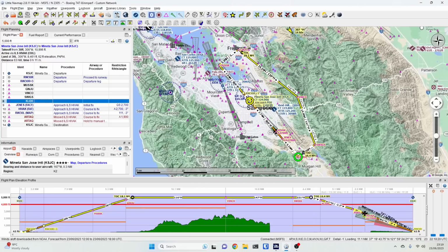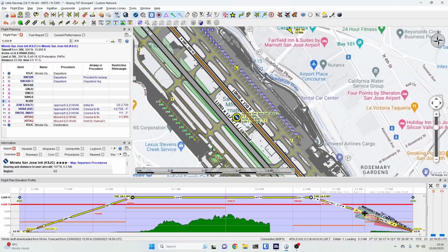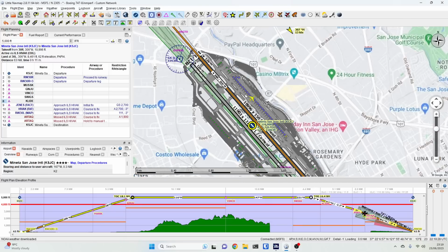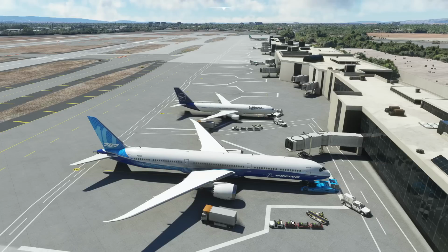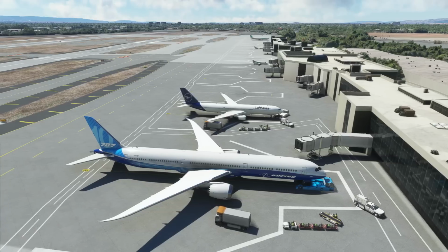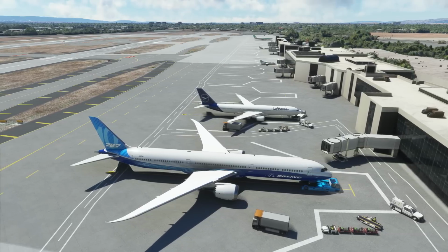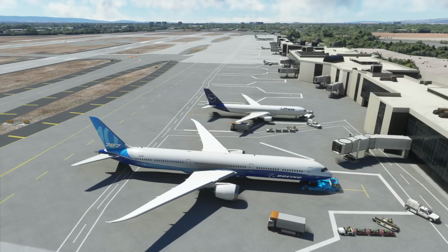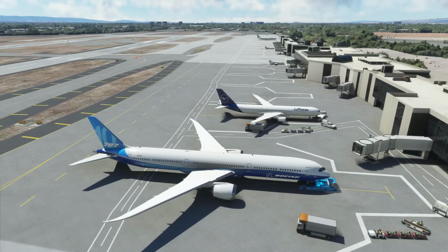So if we remember looking at the airfield here, we want to turn right to go down to runway 30 right, 30 right. So if we have a look, the tractor is nearly engaged. So there it goes, and off the parking brake, which means the aircraft can roll. Obviously, in the real world you do pushback first and you start engines during the pushback. So while we're doing this, we can also get the flaps to 5 degrees.